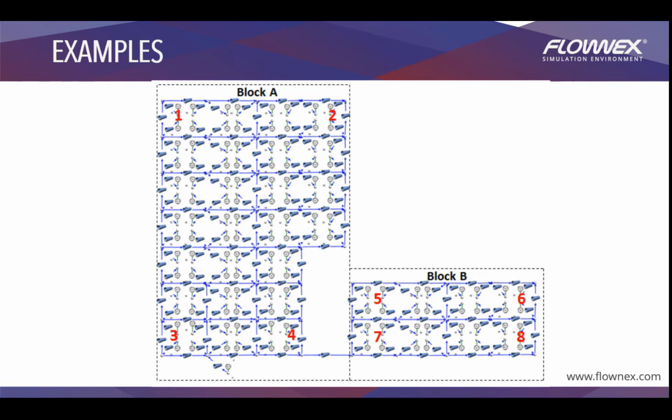So you'll see there are a lot of pipes and a lot of junctions as well. All of this could be modeled in Flownex, and you could identify your pressure drops, your flow rates, and where you need pressures as well. Based on that, you'd make changes to the network or the pipeline in order to meet the pressures and the flow rates that you're looking for using Flownex.